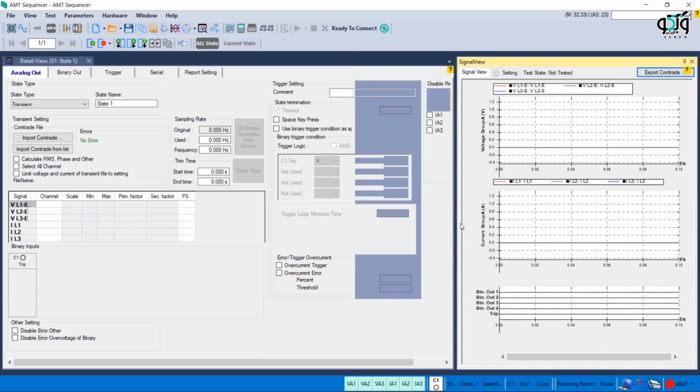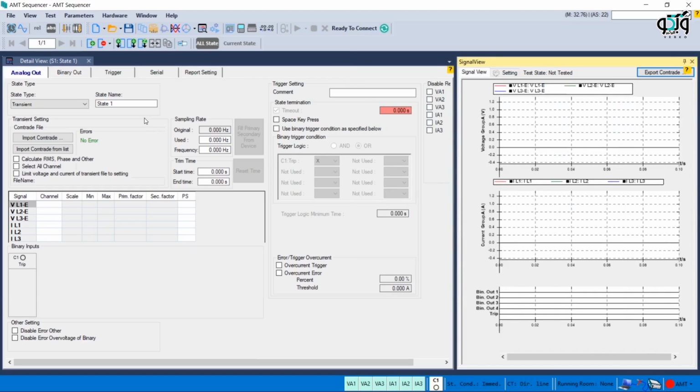When a fault occurs, the relay saves the fault information and moments before the fault as a ComTrade file and provides the user with this file. By using this information, it is possible to view impedance or differential trajectory, or by injecting the same transient signal, simulate the fault moment and test the relay performance again.